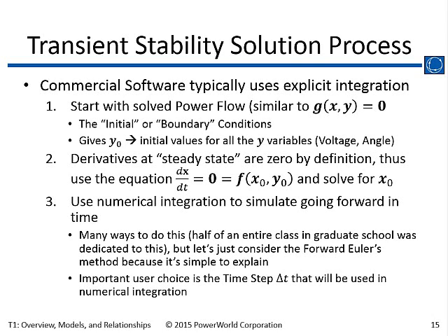If you've used transient stability commercial packages, you know that a lot of times that's not the case. And the reason why that can be the case is when we set these state variables, sometimes the power flow solution has pushed the state variables to limit violations. And then what do you do as a software coder if when you back solve, let's say I get a field voltage of 2.5, and you've got a limit in there that says, no, it can't be higher than 2. What are we supposed to do? These are what we decide as designers. There are different ways you can deal with it, and we'll go through that later on in the course.